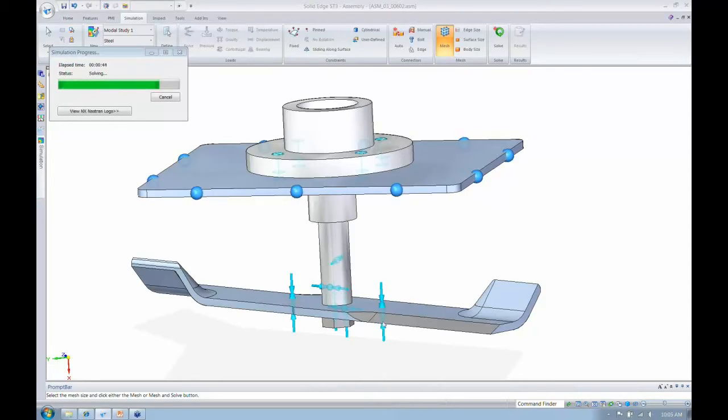Now forced vibration is when I have an input vibration to the system. And let's say I get a ding in this from where I hit a rock or whatever, or I have a grass buildup here, or it just was assembled a little bit off center. Anytime my center of mass is not at my center of rotation, I'm going to have a forced vibration input. And it's going to be at the frequency that this thing is rotating. For this chopper mower, it actually operates at about 3,600 RPM. So if I divide by 60 there, I get 60 hertz. 60 hertz is going to be my input or operating frequency of this mower.